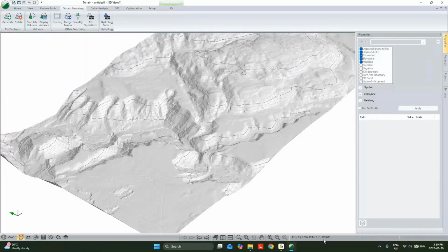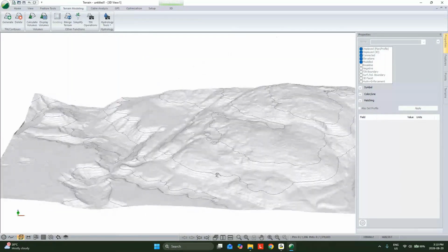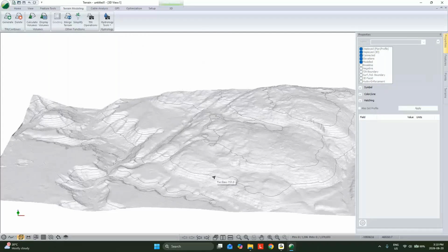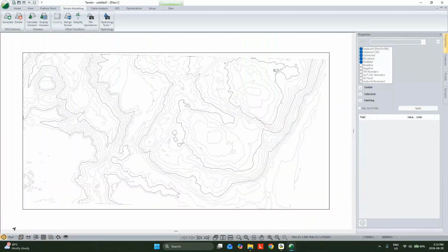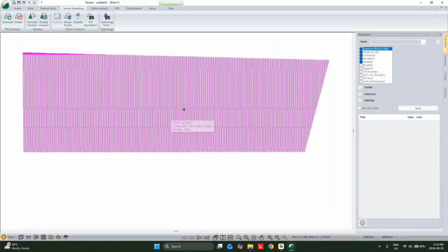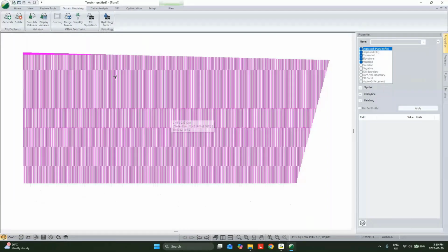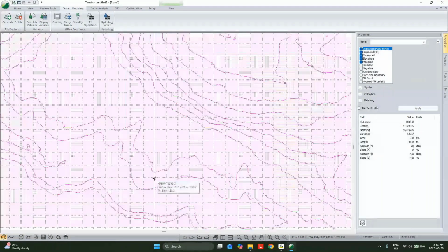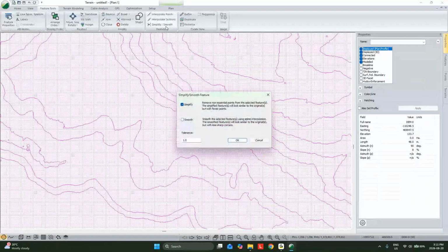So we've got, say, 1.3 million points in this file. If it was much larger, say like 50 million, 100 million points, then we don't have that challenge of really defining where edges are with break lines. We have kind of a data management problem on our hands. So if we wanted to reduce the amount of data that we had in here, if it's DEM data, it's nice where it's all on a regular grid. We could use the simplify tool.